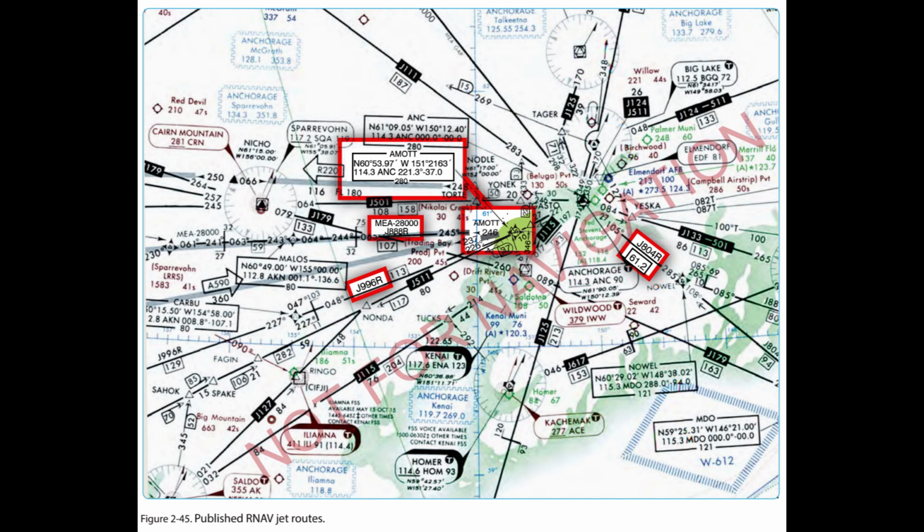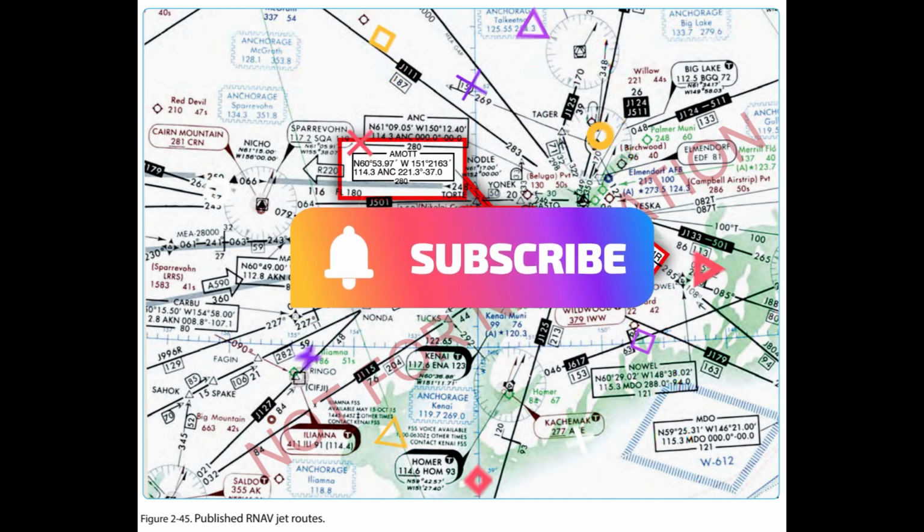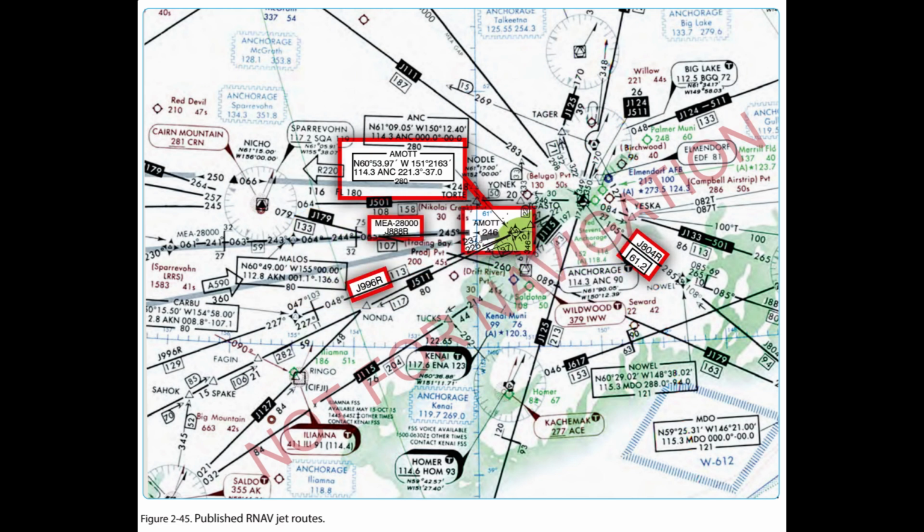Note, when route of flight is described by radio fixes, the pilot is expected to fly a direct course between the points named. Pilots should keep in mind that they are responsible for adhering to obstruction clearance requirements on those segments of direct routes that are outside of controlled airspace. The MEAs and other altitudes shown on low-altitude IFR en route charts pertain to those route segments within controlled airspace, and those altitudes may not meet obstruction clearance criteria when operating off those routes.